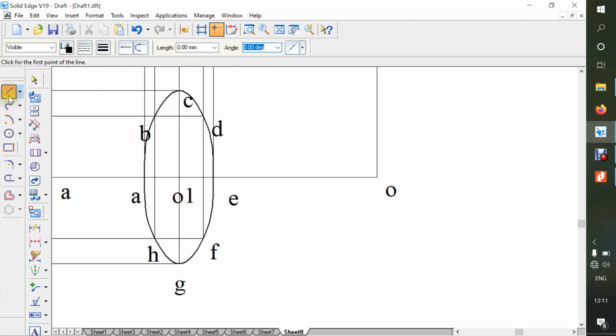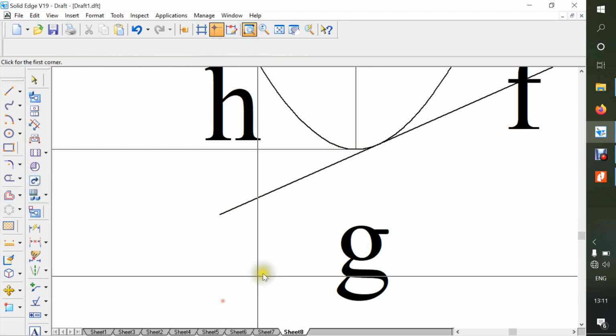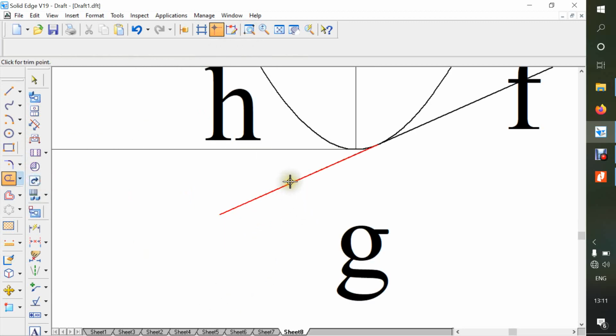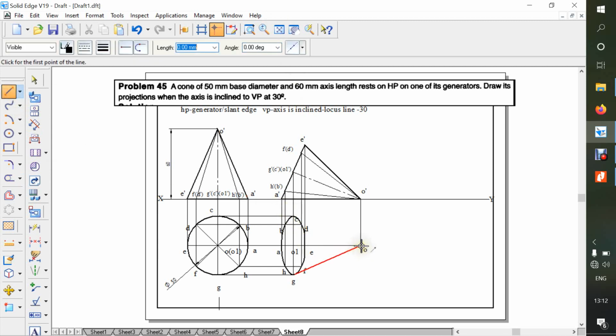So now a line and a dot. So from the O to the tangent symbol. So you can see here tangent symbol. You just drop and go to the trim command and zoom this area and trim this part. So this is how exactly it is visible. Okay, so same, if you want you can just drop a line like this with a tangent.